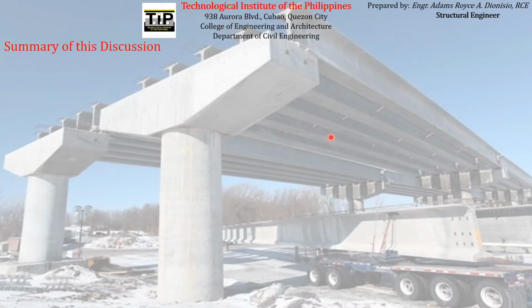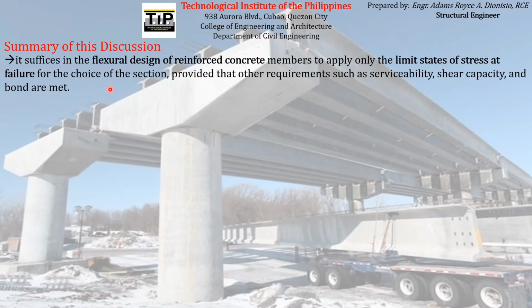So just to recap or summarize our discussion for this meeting, we have learned that it suffices in the flexural design of reinforced concrete members to apply only the limit states of stress at failure for the choice of the section, provided that the other requirements such as serviceability, shear capacity, and bond are met.